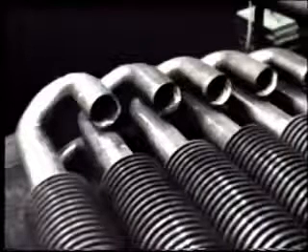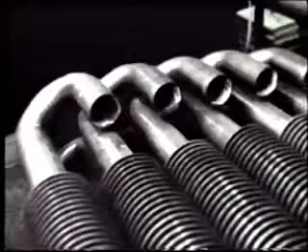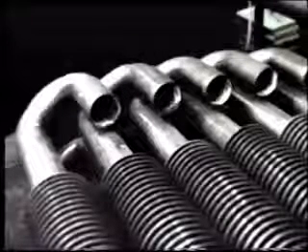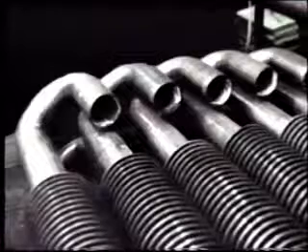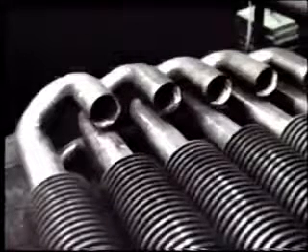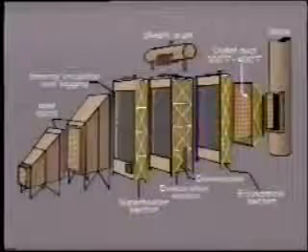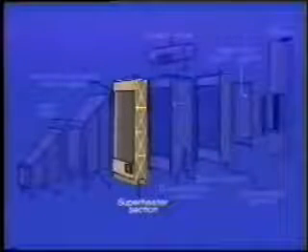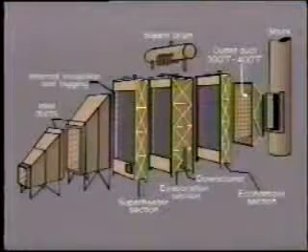Finned tubes are usually employed throughout the HRSG in order to increase the heat transfer surface area on the gas side. We want to extract as much heat as possible from the hot gas. Here we see the bank of superheater tubes which add heat to the steam before it is finally discharged from the boiler. More about this later.